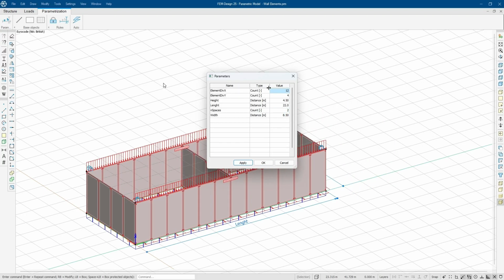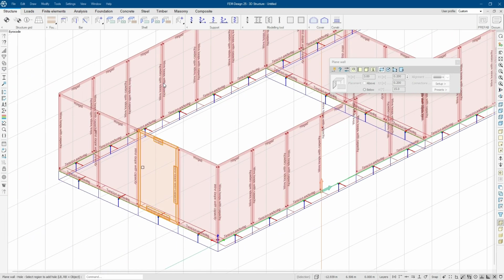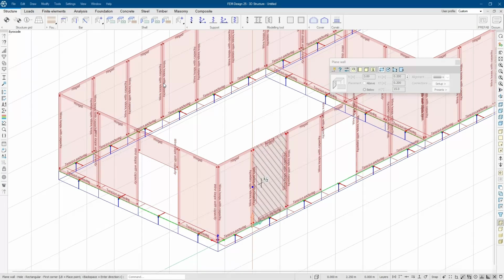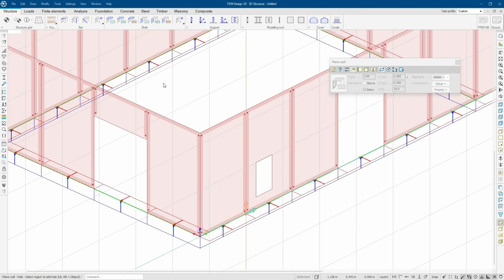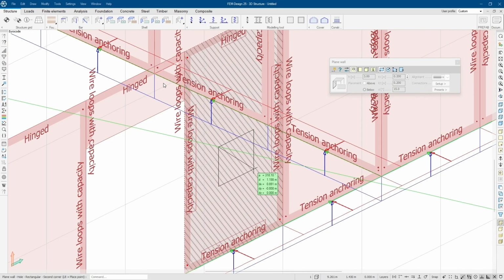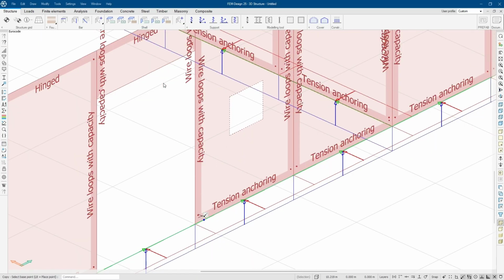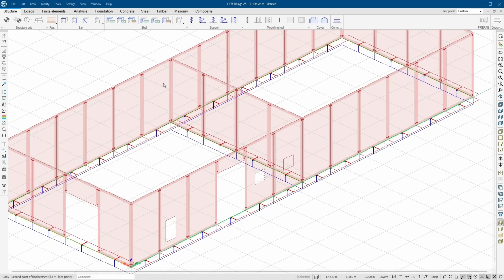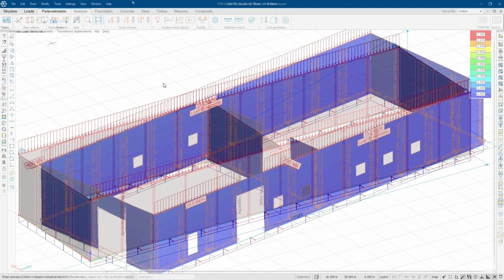And the basic idea is that you never do openings or things that are constant in the parametric block, because they are so easy when you have inserted the block in 3D that you can do those parts which are not repeating, like the doors or windows or openings, so they can be added afterwards. So you just put the repeating part in the parametric module and then add those things which are not repeated. Draw them manually, because otherwise the block will be too complex to use for anything practical. And you can see this is the end result.